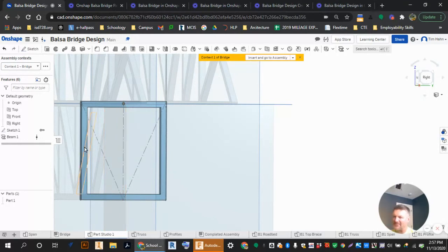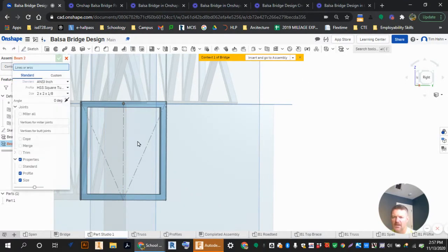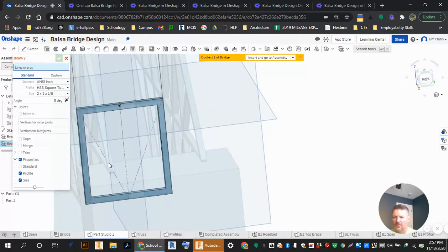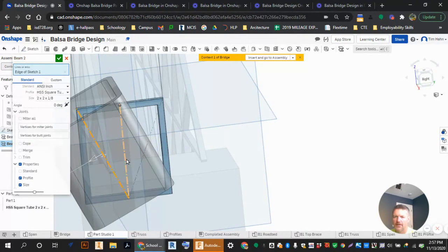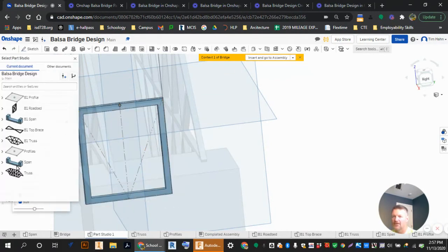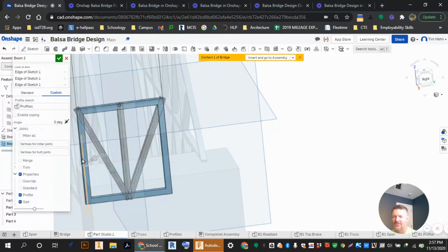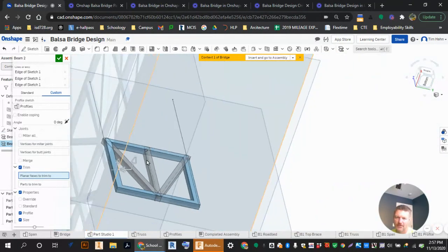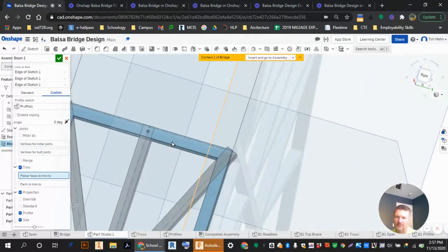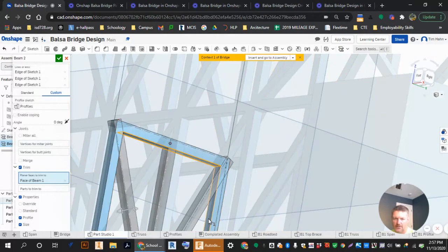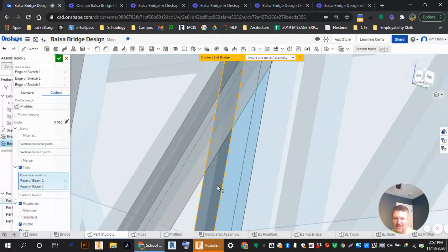Coming up to this beam. Next set of beams. Again, I stayed right in the center and center. So this one here, we're going to put all these in the center. Bing, bing, bing. Custom profile. 1/8 inch by 1/8 inch. And we're going to use trim. You can see these, this is not right, so we need to use trim. And trim by the bottom edge. Trim by this side.